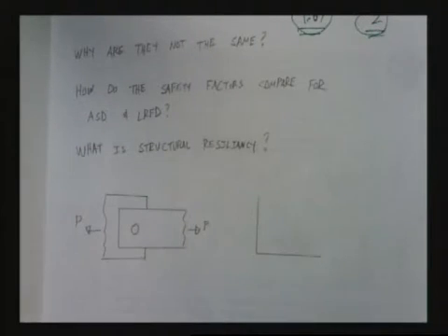the system is going to fail when one of two limits is reached. Either every component has reached its yield, or all the stiffness has been exceeded or used in the system, or when one element or one aspect gets so overloaded that it just breaks. That's this concept, and we're going to see it over and over again. So you might as well learn it now.